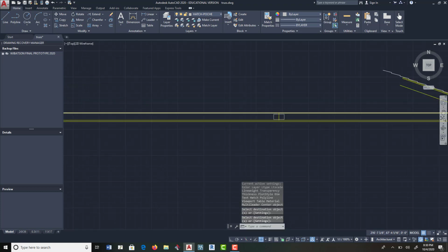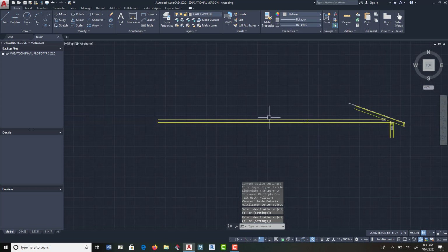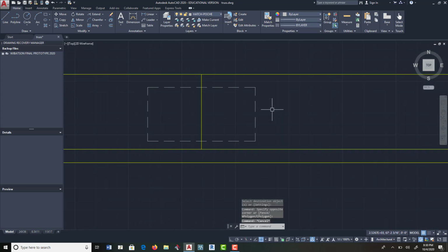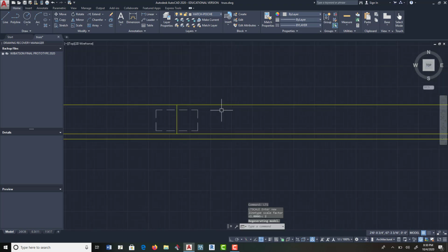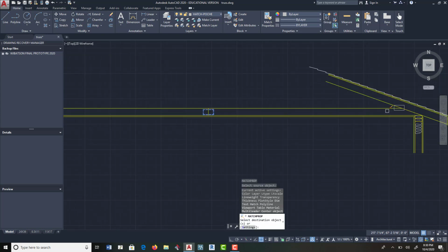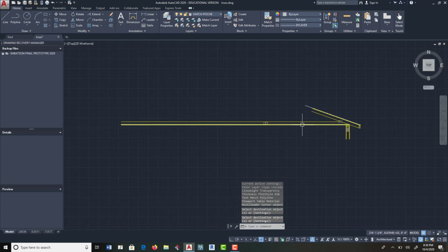So they're going to have one piece here, a short piece, and this long piece, and they're going to splice them right there. And remember, this is going to be dashed, so let's turn that to the dash layer. Good. And that's a good looking dash. It might be too small. Now remember, LTS, we can change it. LTS, line type scale, what is it? It's 1, let's go to 2. That's much better. Okay. So I'm going to match properties, MA, enter. I'm going to match that one with that one. There you go. So now I've got two of those pieces.